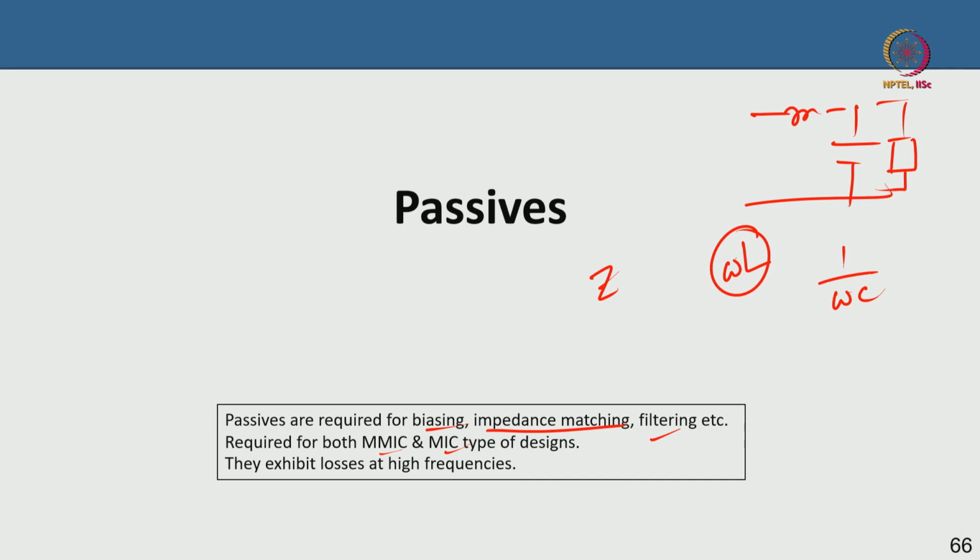For an inductor, it means that at higher and higher frequency, it is a high impedance for an AC signal. However, with higher and higher frequency, the impedance of a capacitor reduces, so it becomes like a short. At very high frequency, capacitors will act as a shunt path, and inductors will impede the flow of AC, so they will try to block it. Just keep that in mind: at higher frequency, if you have a dielectric, for instance, the capacitive coupling will tend to dominate. This is a key fact that you need to keep in mind as we talk about many passives, as you will see.